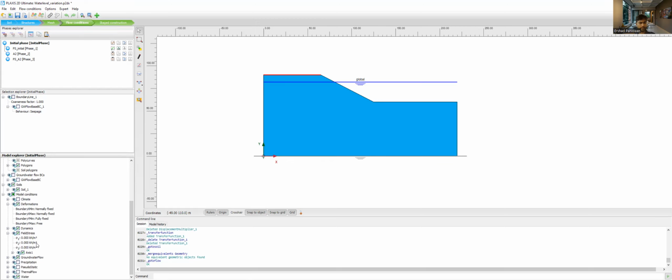So now we are moving to the field stage. We can input here in the field stage, below, the groundwater flow. This groundwater flow means a discrete boundary condition, where the boundary is always closed in the lower portion of the model. In the precipitation option, we can input the rainfall data. It might be constant, dynamic, or harmonic. For pseudo-static, if we want to analyze the peak ground acceleration, we can input the peak ground acceleration.